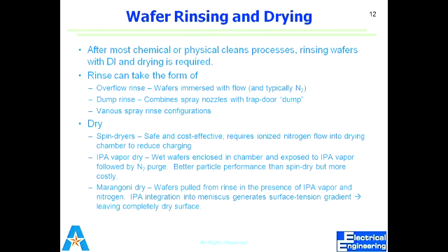So ionized gas restricts the wafer from getting charged. If you are not using the ionized nitrogen gas, then when you take it out it will be charged, and the charged surface always attracts particles towards its surface. So to block that charge, we use the ionized nitrogen gas.